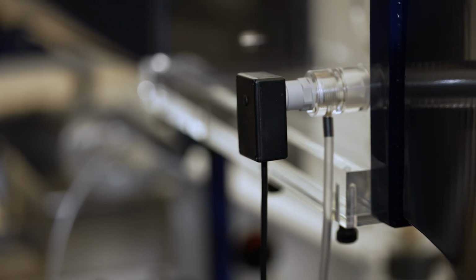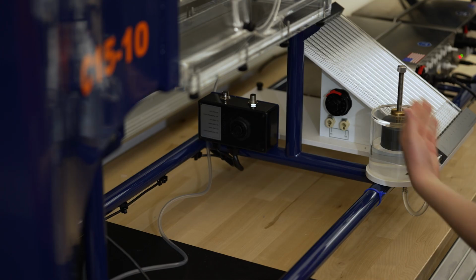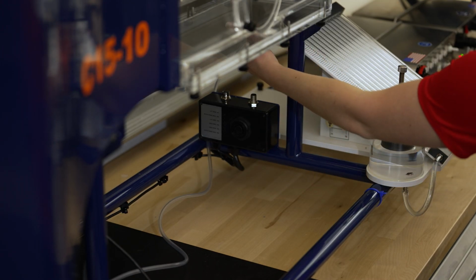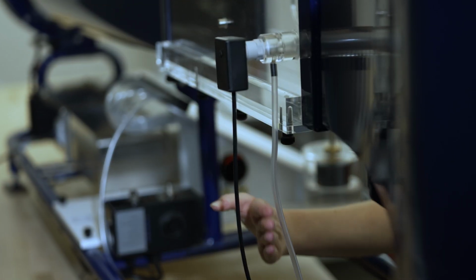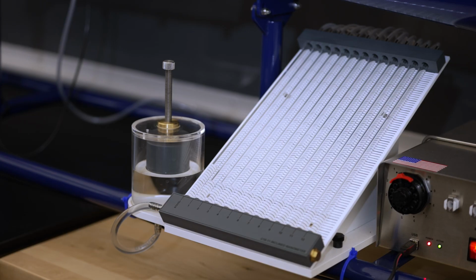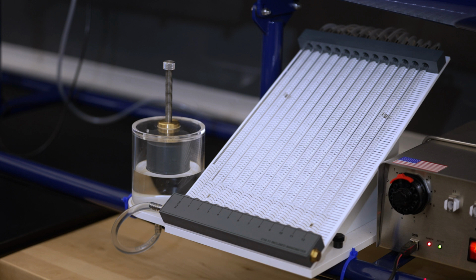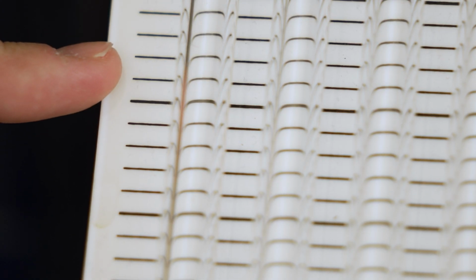A static pressure sensor is located on the far side at the onset of the test region. This sensor is connected to the incline manometer and the electric manometer. The next component, the incline manometer, can be utilized to measure the static pressure head loss within the tunnel. The incline manometer uses water, features a 30-degree slope, and has 2 millimeter markings and 10 millimeter markings.